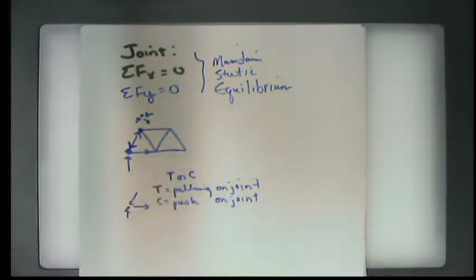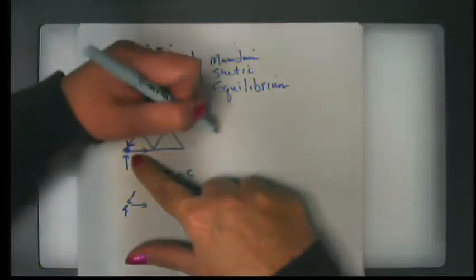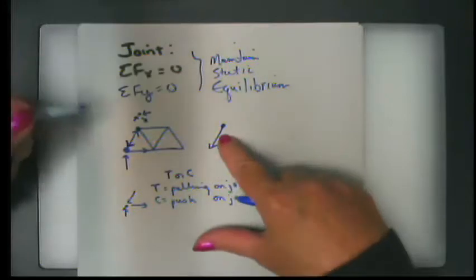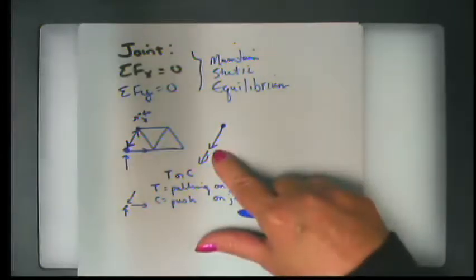That's because, once again, that structural member has to be in static equilibrium. The overall force in that joint from an outside perspective is 0. So whether it's pushing or pulling on a joint is how you determine the direction. But when you go to the other end, to the other joint, it's going to change direction to maintain pushing or pulling. And if you think about it, if we had this force going downward, that would actually rupture that joint, wouldn't it?